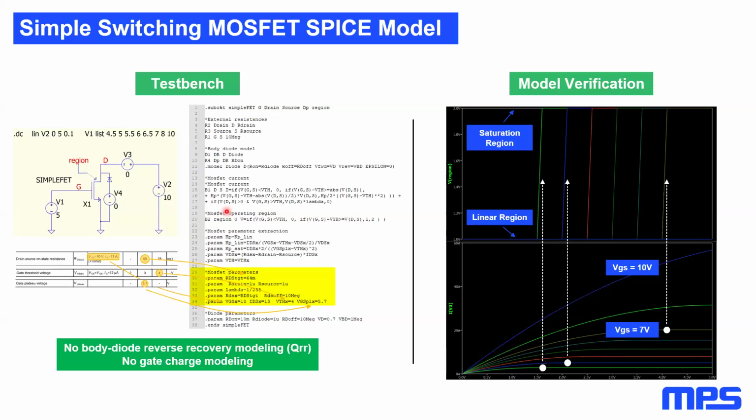If the internal drain and source resistances are known, the model can be further refined. The parasitic capacitance can also be added externally and can be modeled as complex as needed. Regarding the body diode, we opted for a very simple and practical ideal diode model, which is available in the QSpice native library.